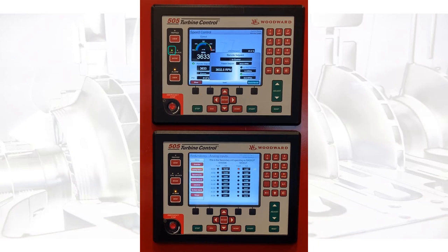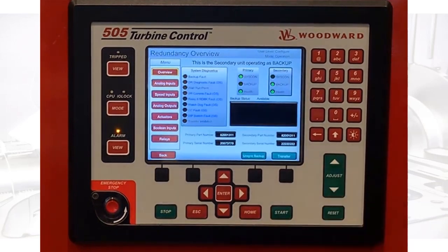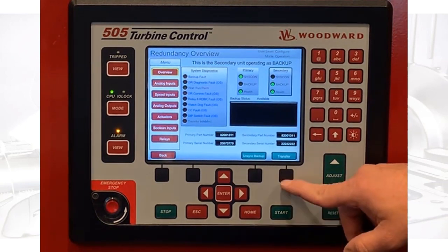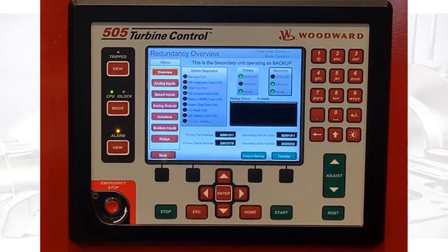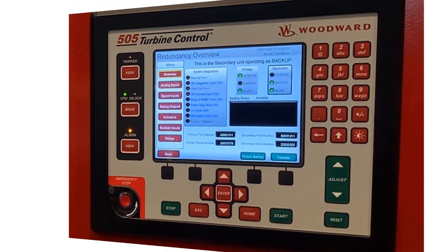The new syscon keeps control with the remote speed set point from the analog input on the healthy circuit. The failed unit is available to become the syscon because in this case a failed analog input will not result in a system trip. Therefore, it is available to become syscon if a critical error occurs, and it will take control of the system but with limited functionality due to the failed analog input.